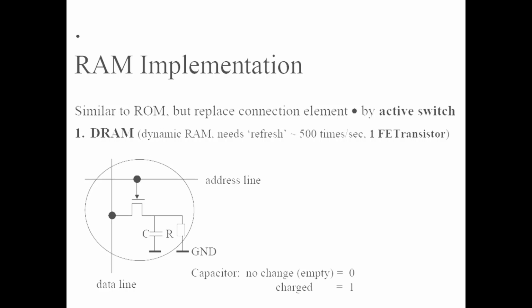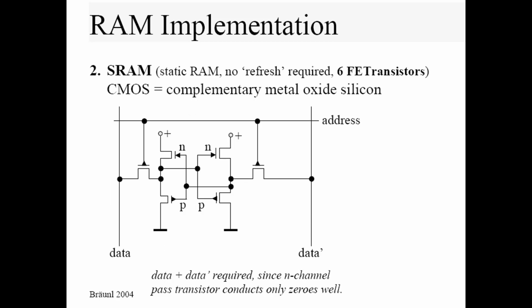Example implementation: in a typical 1T-DRAM cell, the gate of the FET is connected to the word line. The source or drain of the FET is connected to the bit line. The other terminal of the capacitor is connected to a reference voltage, usually ground. Static Random Access Memory or SRAM is commonly implemented using a 6-transistor, or 6T, configuration. This design is known for its speed and stability.